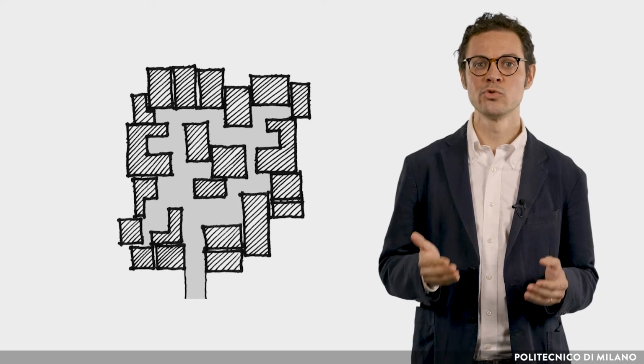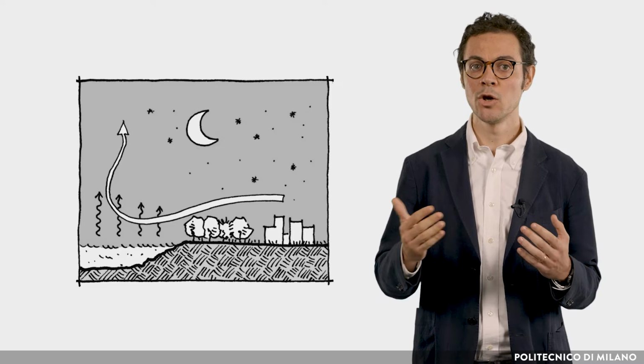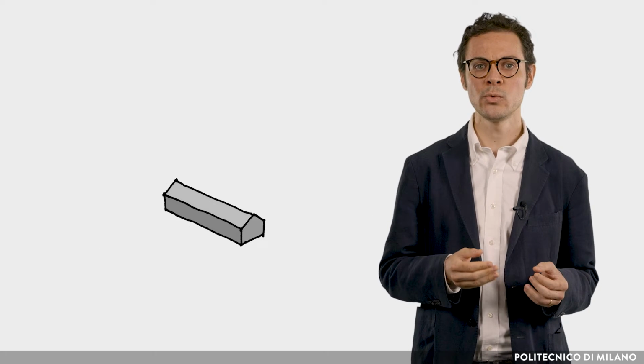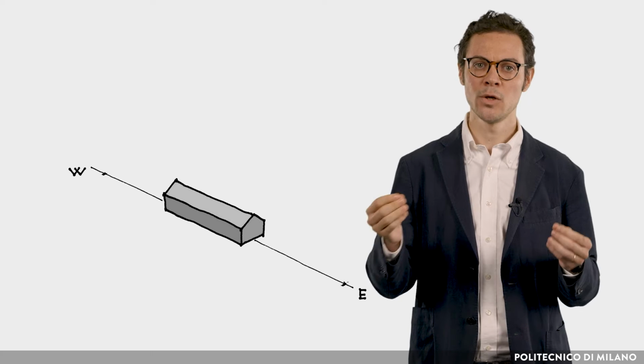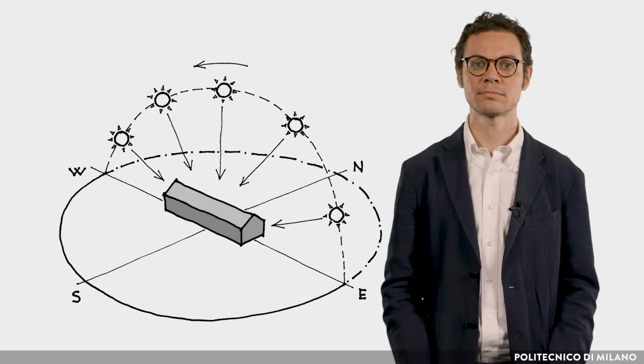Housing layouts should be in compact urban form. Compact planning minimizes the solar exposure of individual houses and also reduces solar heat gain by providing mutual shading and by reducing external surface areas. Buildings should be compact, but allowing good natural night ventilation, and should be oriented with the long axis running, where possible, east-west to provide effective shading.